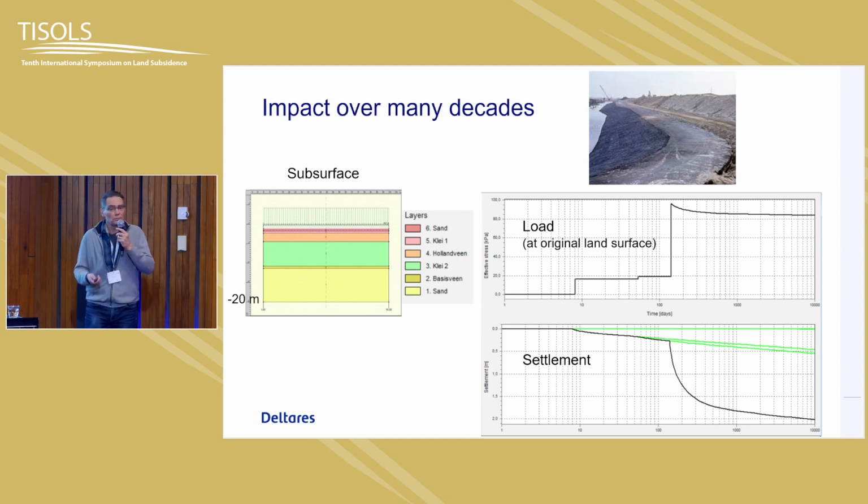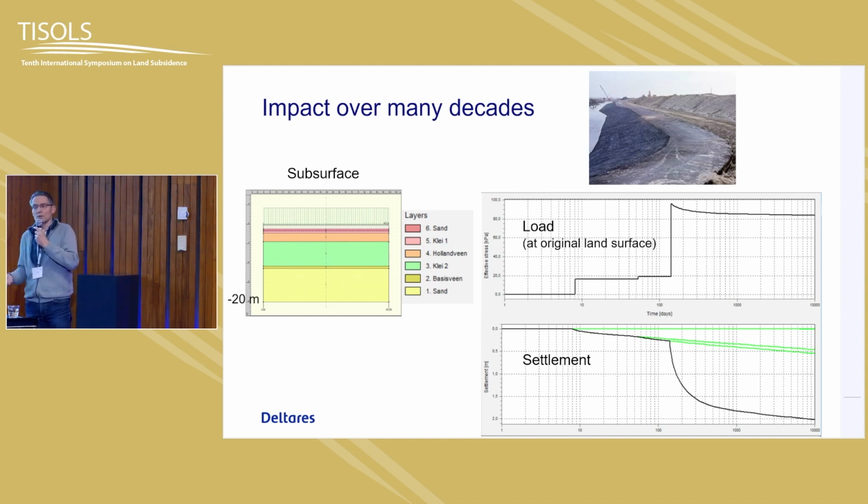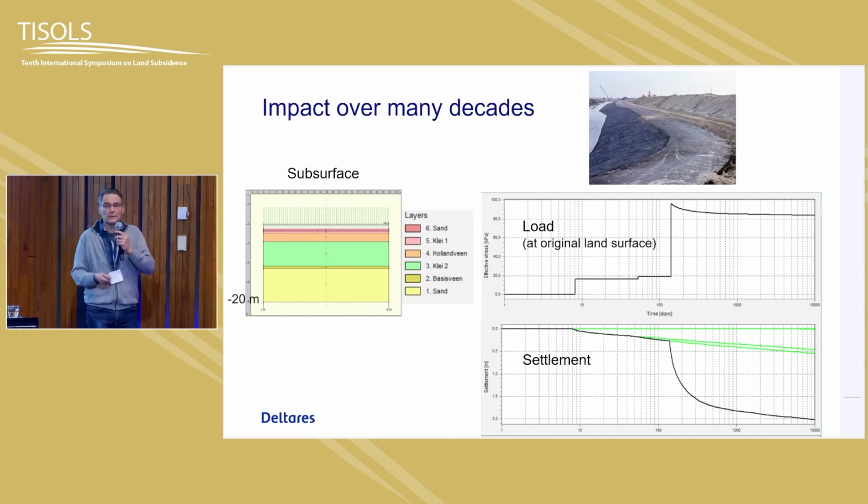Of course, when you do that, the subsidence or the settlement is taken into account by building up the soil, by adding loads. You want to end up at a certain level, but you can't wait 30 years before you can live there. So this is done for a couple of years or so of construction, and then the total surcharge is settled to a certain level, maybe here after a year or so. And then, of course, you have to put in the pavement and the road, etc. And then you start living there.